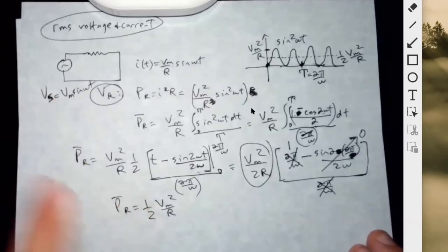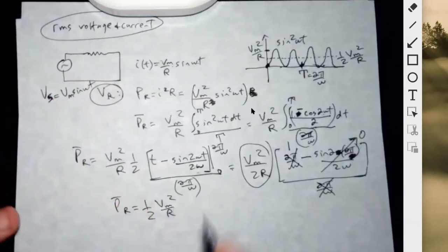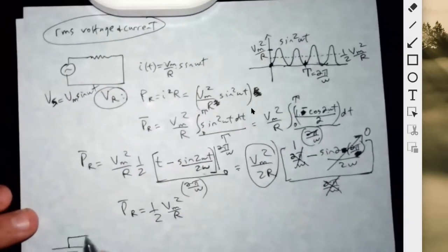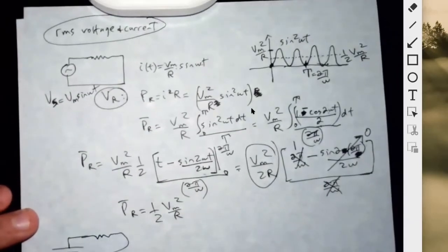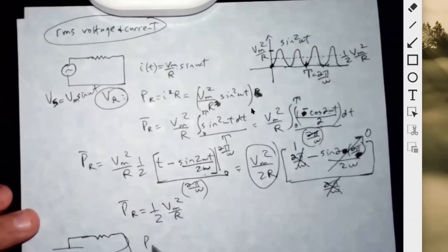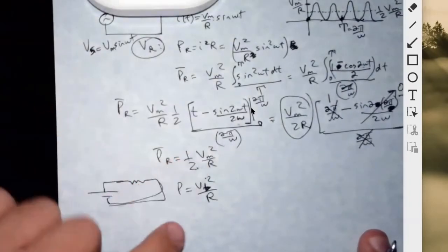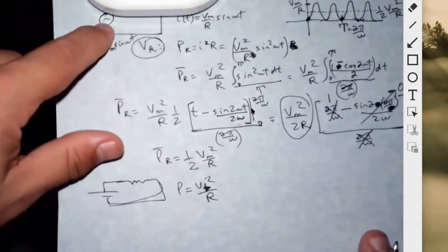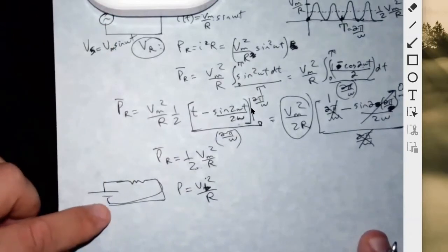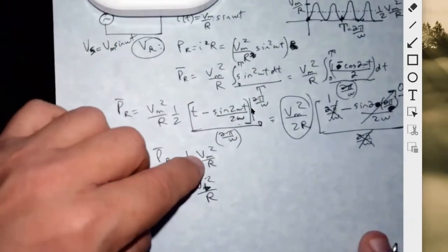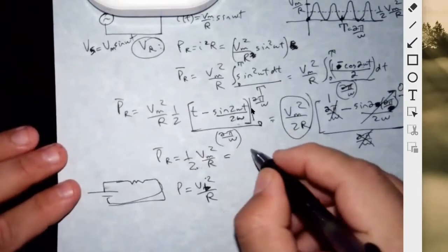But the effective voltage is not really Vm, because in a DC circuit, the power would have been V battery squared over R, right? So there would be no 2 in that function. So in other words, if we want to compare an AC source to a DC source, we can take the 2 inside of the Vm and then rewrite it like this.